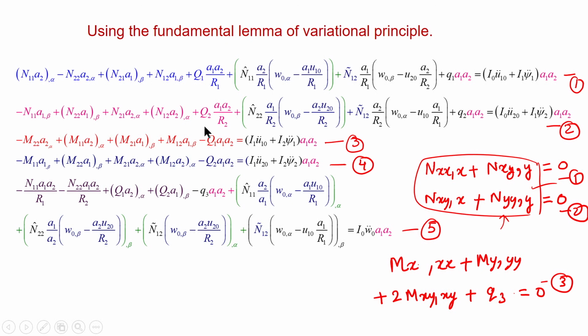So, we cannot solve independently, we cannot say that we solve only the third, fourth and fifth equations together and 1 and 2 remain. No, they will affect 1 and 2. Basically, in a shell, if the shell is thin, even a bending effect or a bending force may cause extension, meaning significant stretching. In the plate it is not so.